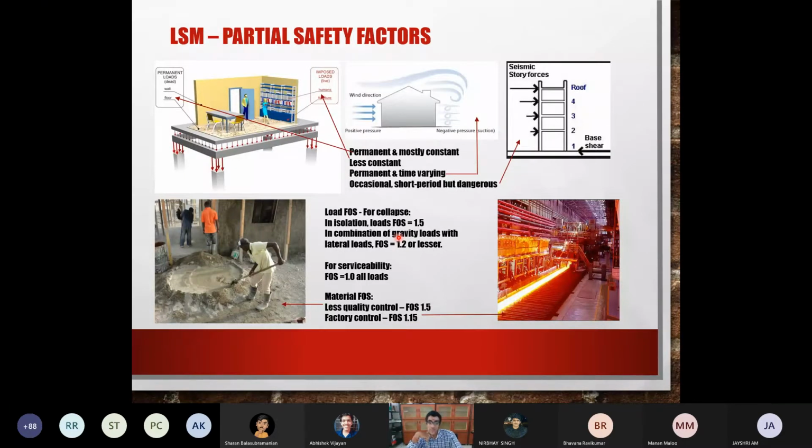There's a more rational reason. Okay, by the way, the clue for that is whenever you design for wind, it is designed based on the recorded peak wind loads. Similarly for seismic also, based on whatever is available on record. So based on that, you adopt a historically peak value, and based on that you design it. Okay, so that is the clue.